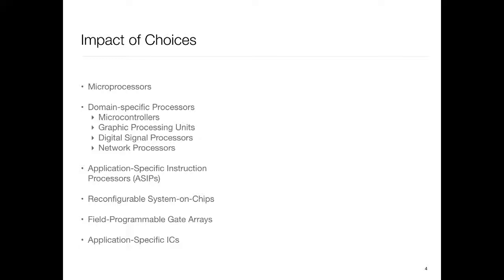How you partition it, there are tools called hardware-software co-design tools, which work on it. The idea is that my starting point is my algorithm, and then the tools take care of dividing it up and mapping the part which is supposed to go into software into the processor, and the part that's supposed to go into hardware into the FPGA. Later on you change your mind and say, move this thing from software to hardware, rerun the tool, and it does that. So for many things, if you are able to afford those kinds of tools, these things exist. Then next up, FPGAs, which are basically reconfigurable SoCs but without the processor, so just the FPGA.